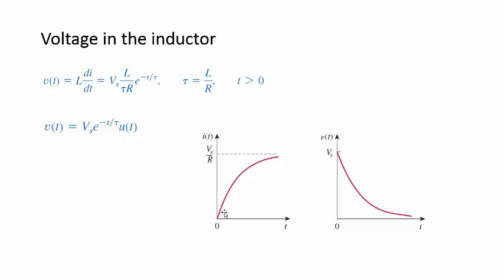What's interesting to see here is that the current is going from 0 to something that builds, because current, once you apply a signal, doesn't change right away, but eventually will become the max current in the circuit, correct? Because the inductor becomes a short. So if you have the maximum current and the inductor has become virtually a short, what must the voltage do? The voltage must get less and less until the voltage across the inductor is about 0.